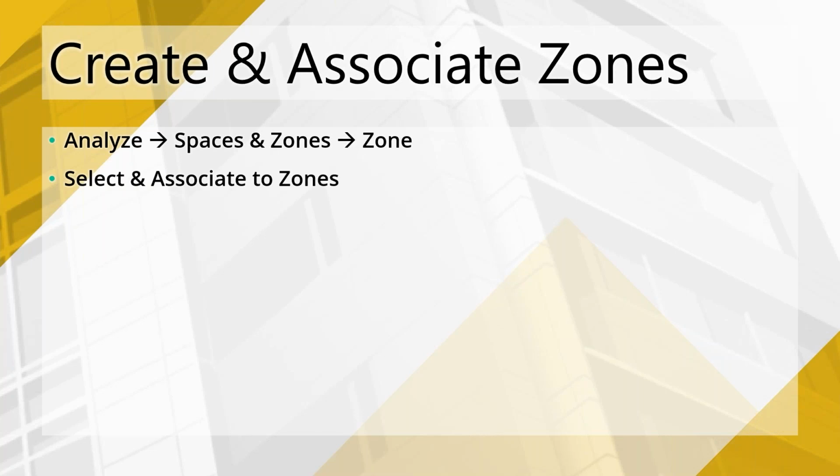For the zones, you can either create a new zone and then associate spaces to it, or you can select the spaces first and then create a zone and it automatically builds that association. And then I like to tag and name my zones in some consistent way. That way I can identify them, and the views that we'll be working in will actually help us identify them as well because of the color filling that we've got pre-baked inside of there.